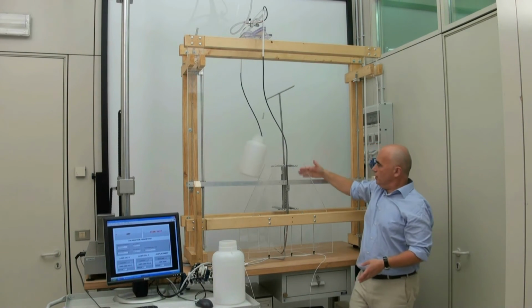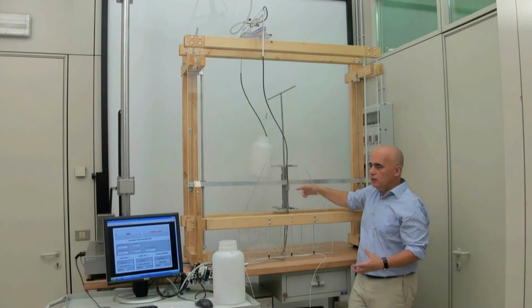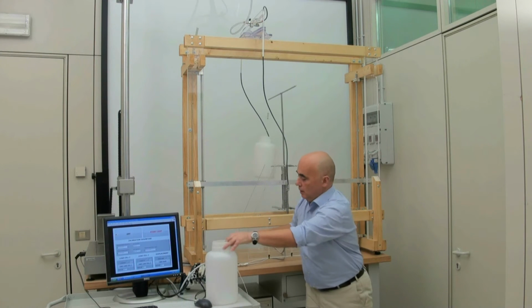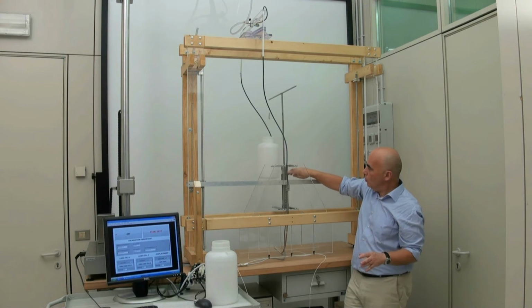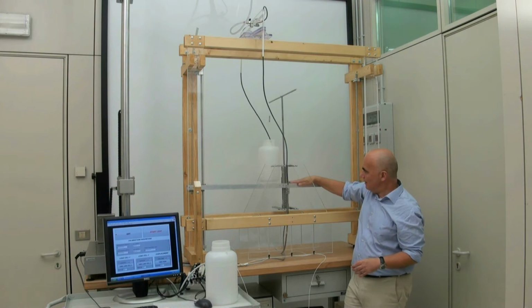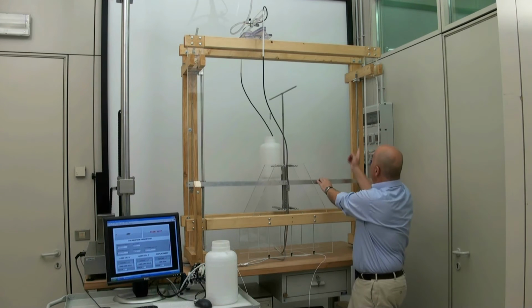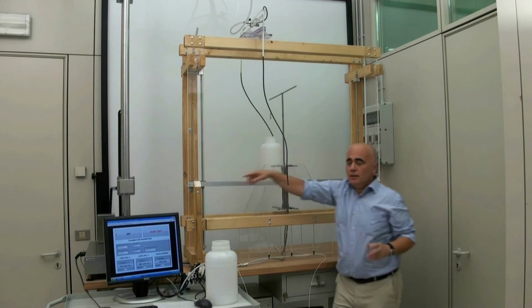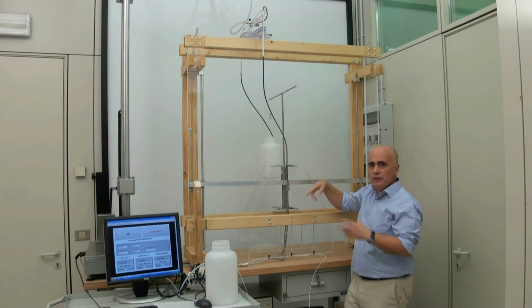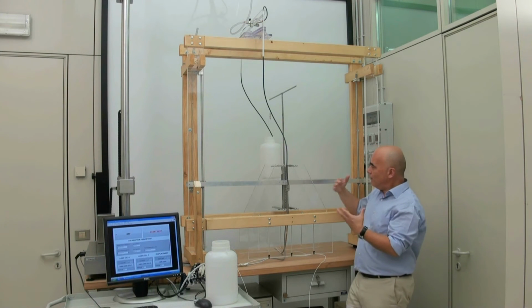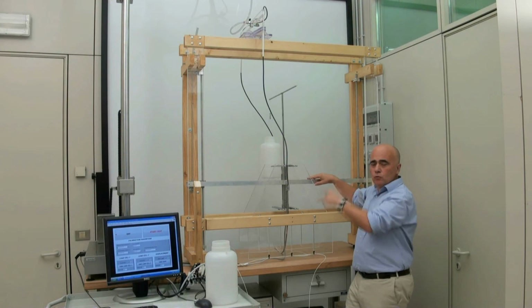What we measure here is the load and the vertical displacement using this non-contact transducer, and the acquisition is this one. The sliding sleeve is this piece and is realized with many rollers coated with Teflon, and the elastic spring is provided by this rigid bar hung with two linear elastic springs. So our purpose is to load the system, measure displacement, and see how buckling evolves. After buckling, we will see that this rigid bar goes upward due to the Eshelby-like force.